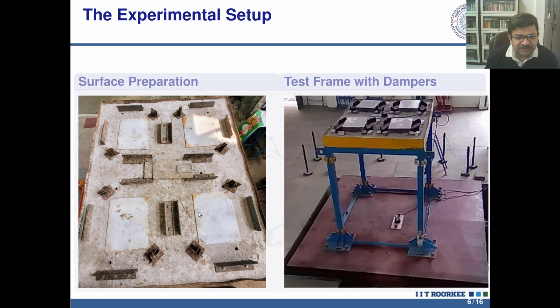So the first thing that we need to look at is these small concrete blocks that you see here. Now, if I place it on a concrete to concrete friction interface, the coefficient of friction is very high, of the order of 0.8 or more. So practically the block will not slide. You might have experienced concrete blocks on top of each other, they are not very easy sliding systems. Now the whole idea of a tuned mass damper is that the auxiliary mass should vibrate easily. So how do we do that?